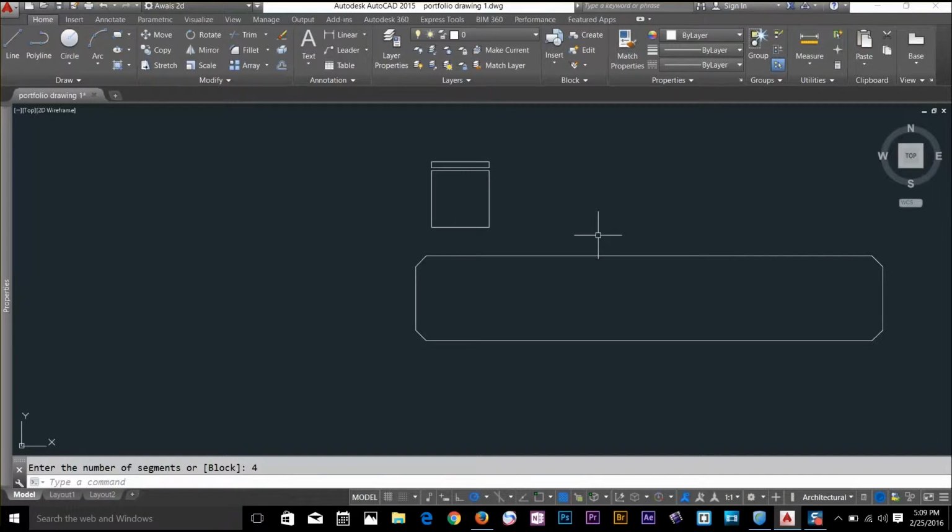These points are displayed as single pixels, and they are hard to see. It will be hard to see if the layer is the same as the object. So what I want to do is change the style of the points so we can look at them. To do that, I want to type a little-known command, which is DDPTYPE,